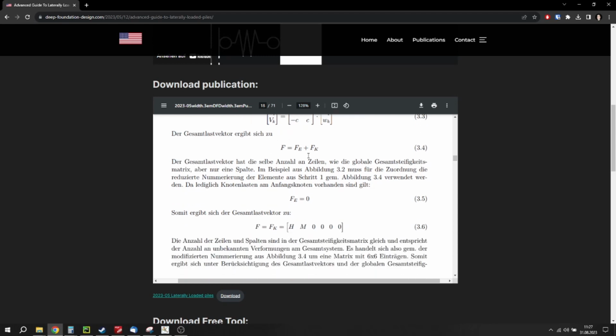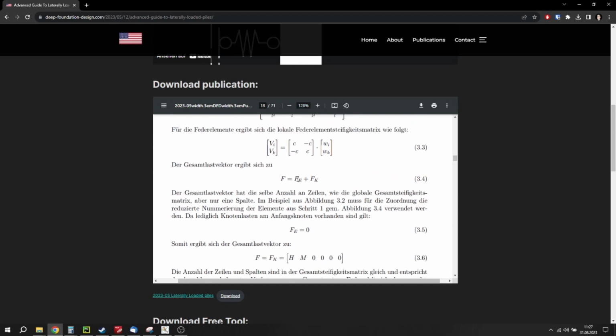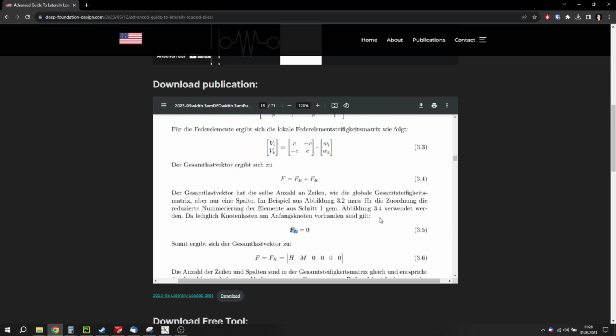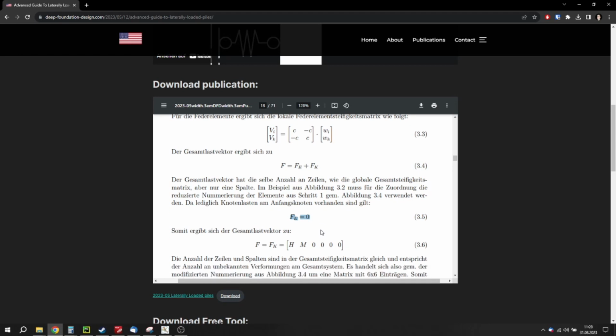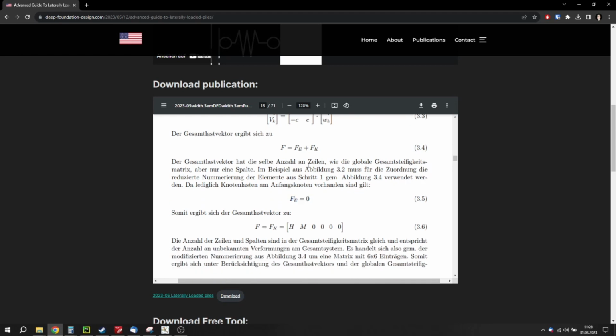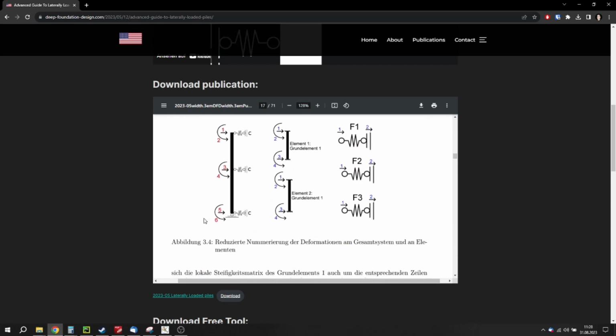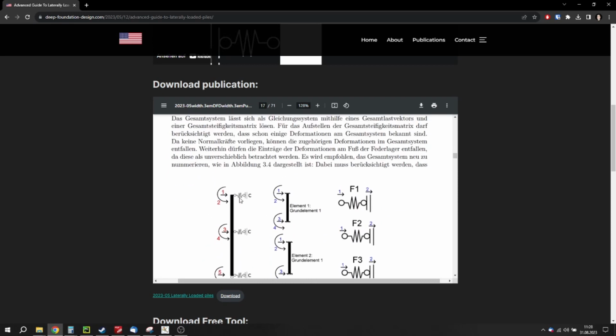Okay. And the next thing we can do is, in this method, you can consider 2 sorts of vectors. It's going to be the element vector and the node vector. And since there is no loading apart from the loading of the top, basically what we can consider is we can say, okay, Fe is 0 because there is no loading on any of these elements, and it's just going to be the node vector. And for the node vector, it's even easier because in none of these other nodes there is going to be any forces attaching. It's just going to be top loaded.